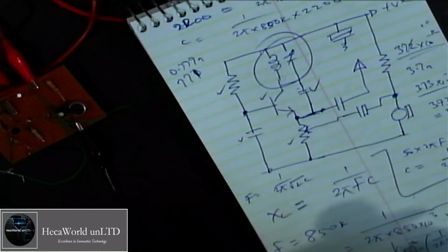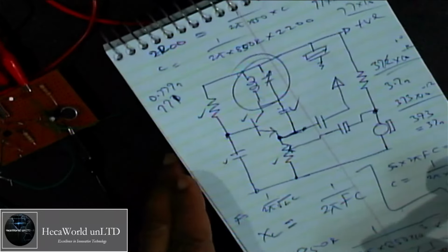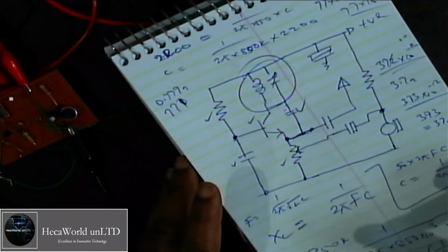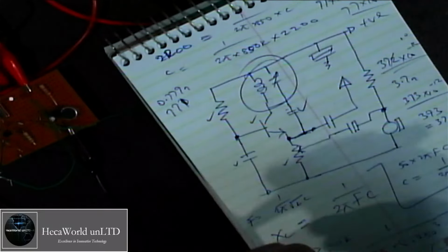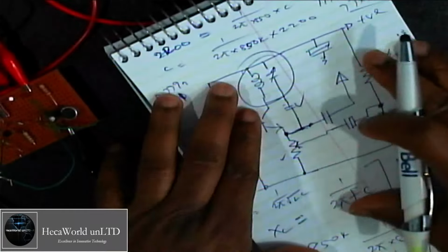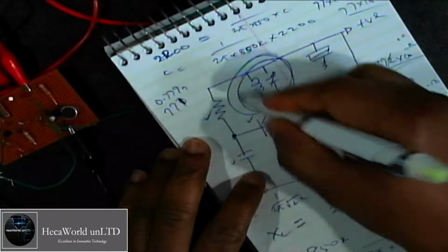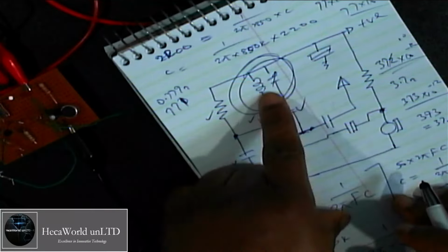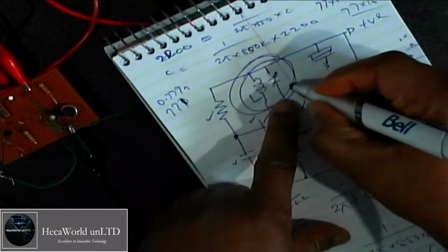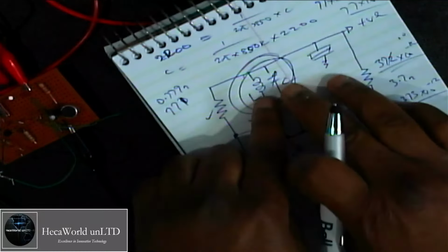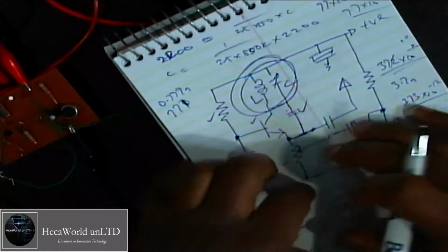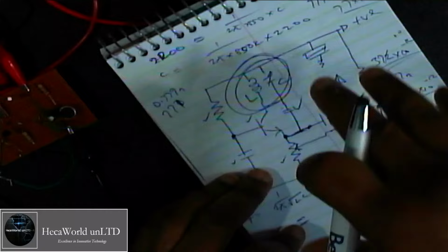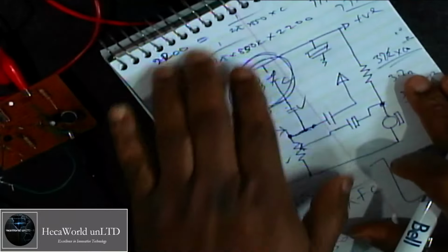We're going to continue the episode we started 2 weeks ago, and this is on the basic electronics tutorial. So today we're going to look at a radio transmitter. You will remember from last week this circuit diagram, we say that this portion here is the tank circuit or the resonance circuit, where we have an inductor and a capacitor. With these two in place, we can build a frequency determining network that helps us broadcast or transmit on this amplifier or this transmitter here.